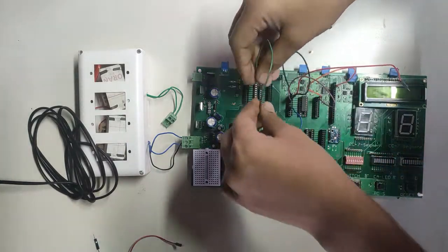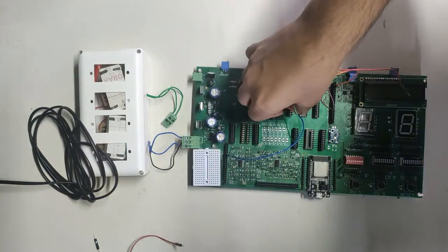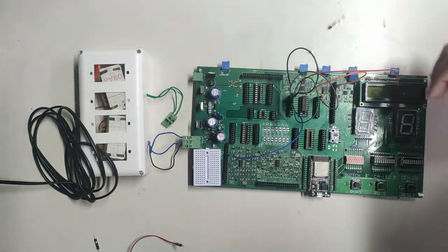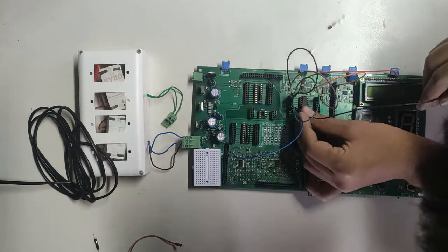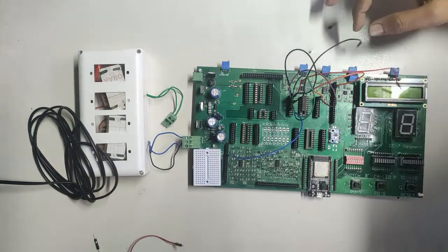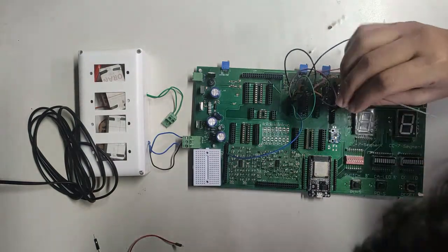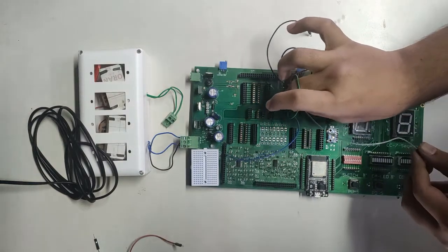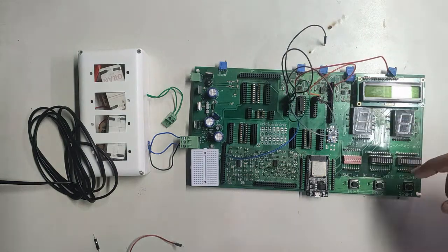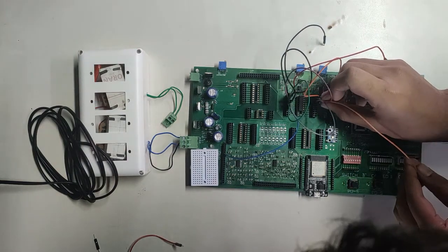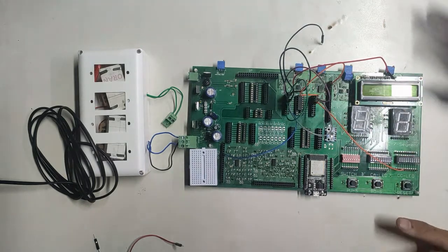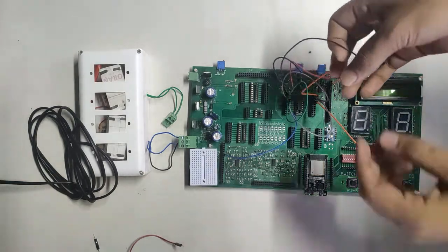Now we are shorting the second NAND gate for the second input. The second input can be given through the black wire. The output of the second NAND gate is again given as input to the third NAND gate, and the output of the third NAND gate is our actual required output. So the final output must perform the OR operation. Now let us check if it is true or not.